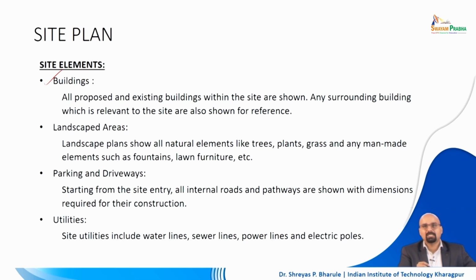Taking that example into consideration, you may also put down that particular building from where the reference point was identified to draft the building. So that's really important. All the buildings which are relevant to your design and site are to be placed on the site plan.